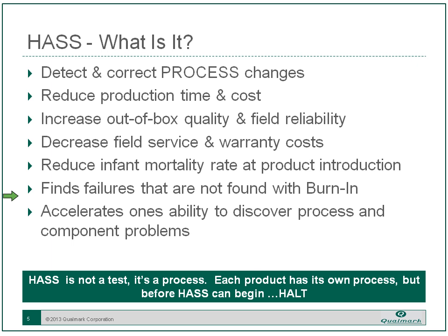You'll find failures that you can't find with burn-in. As many of you know, burn-in doesn't do a whole lot anymore because we figured out how to make ICs, and the purely chemical processes that burn-in spots aren't a major factor in what makes products fail in the field.